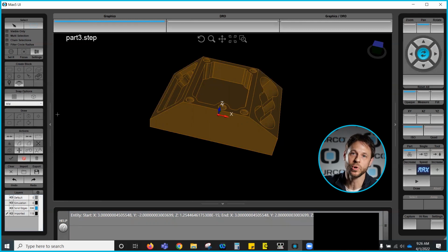Because we are now moving geometry, and the software knows that we're machinists here. We're not dealing in general numbers. We need exact points. It's not going to allow us to transform, rotate, or anything without exact points or exact numbers. So it is going to force us to use our snap to object. That way we can't do something that we can't really replicate easily on the machine. So I'm going to go ahead and turn that on.